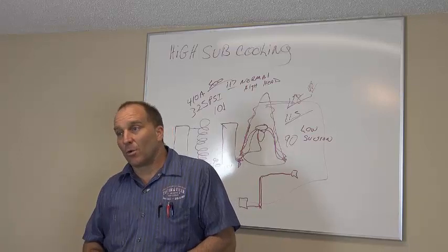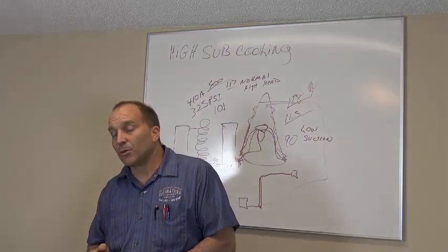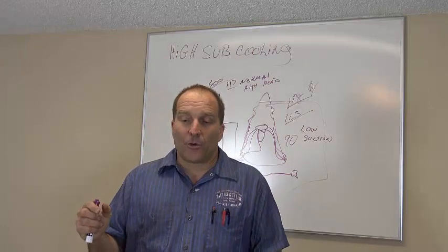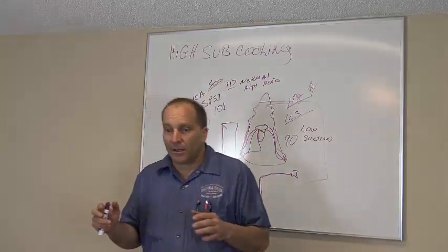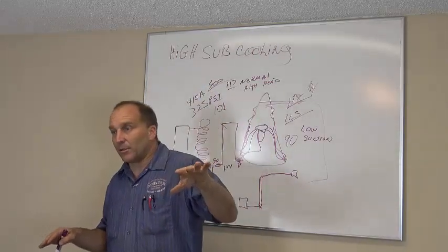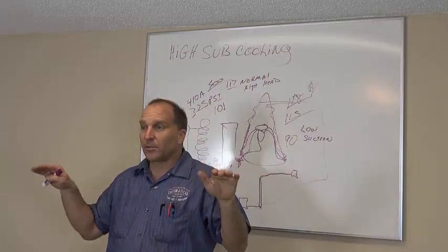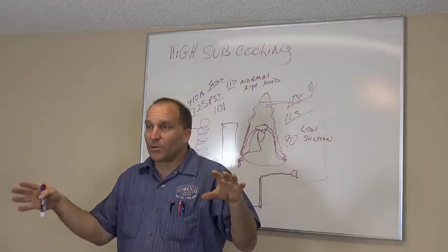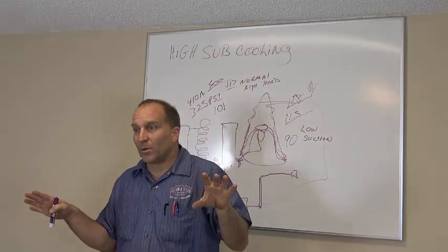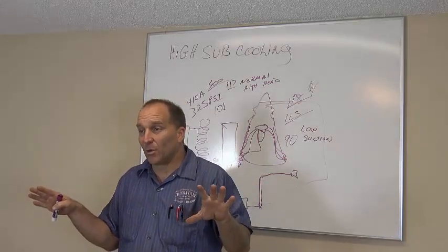I'm going to go through one quick one for you here. You go to a job and you have a normal looking head pressure, a normal looking suction pressure, fairly normal superheat, and a fairly normal subcooling, or a really high subcooling basically.